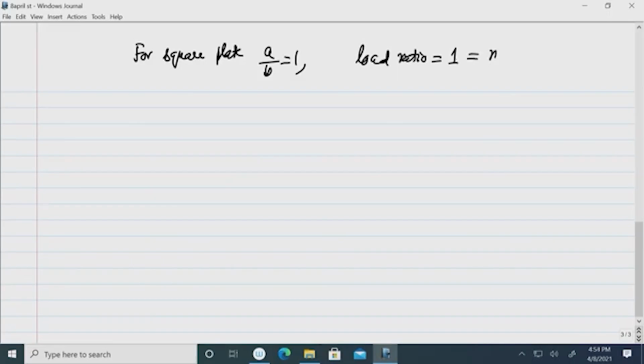Now, after substituting this in the previous expression for N_x, we now get N_x equal to (m² + n²) π² D by a². So, a simple expression is now found for N_x.